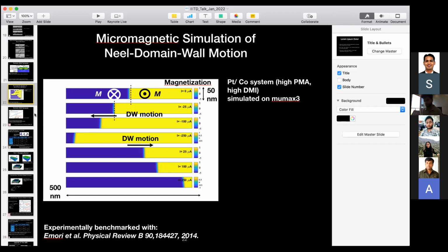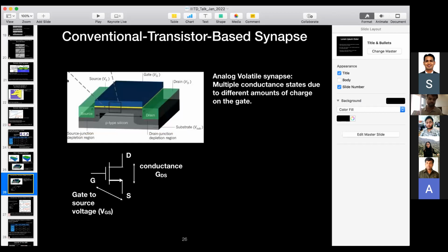Just a guess, but we can have a leakage in the case of charge. Exactly. The same thing is true between SRAM and a magnetic hard drive, right? Or between SRAM and a flash memory. SRAM is a leaky system, or DRAM is a leaky system. In the case of magnetism, the leakage problem won't be there. Right, so everything comes at a cost. It's easier and cheaper to build transistor-based systems, but then you have a leakage problem. On the other hand, in spintronics, you don't have the leakage problem.